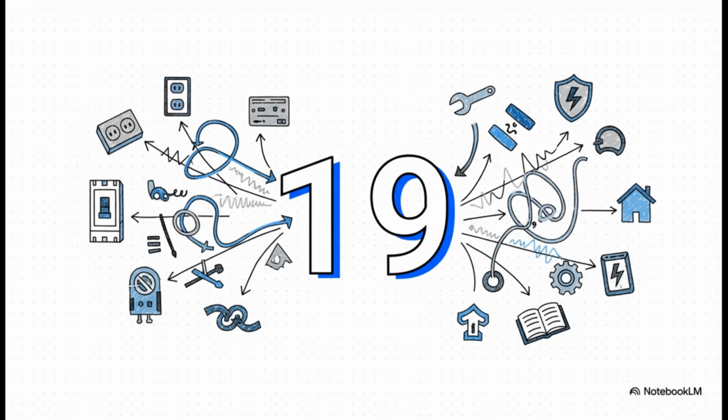We go from circuits with tiny amounts of energy to circuits with massive energy levels, where the danger is just exponential. It's a completely different world. When you cross that threshold of 1,000 volts AC or 1,500 volts DC, the general rules of chapters 2 and 3 are fundamentally inadequate. The properties of electricity literally change at that level. So you need totally new rules. You need specialized rules, documented in articles like over 1,000 volts general, which is Article 495.